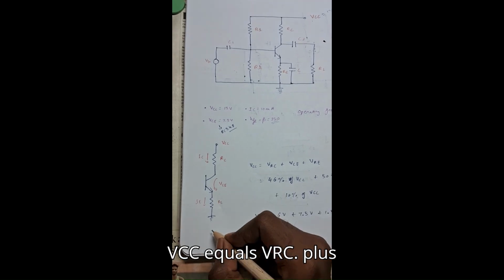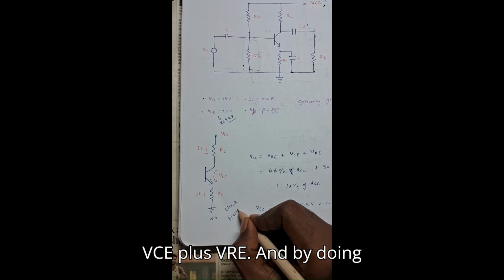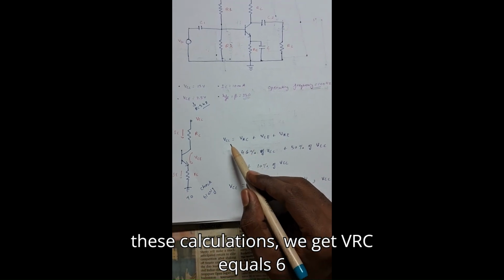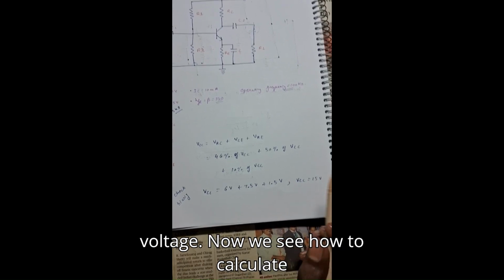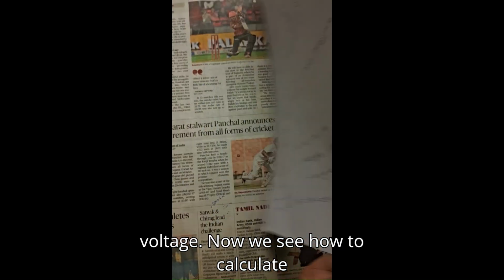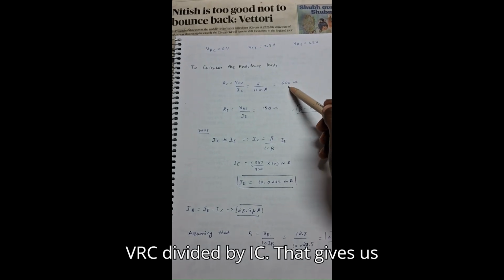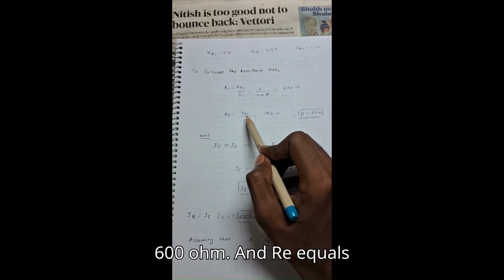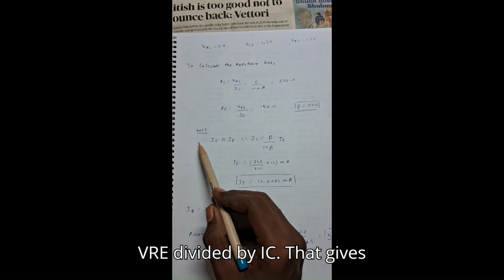VCC equals VRC plus VCE plus VRE. By doing these calculations, we get VRC equals 6 V and VRE equals 1.5 V. Now we see how to calculate the resistance values. RC equals VRC divided by IC, which gives us 600 ohm, and RE equals VRE divided by IC, which gives 150 ohm.